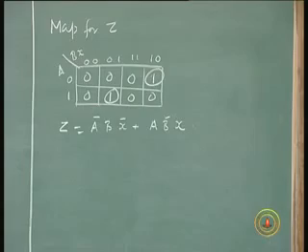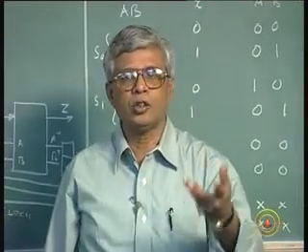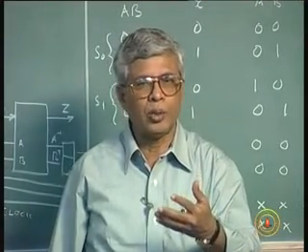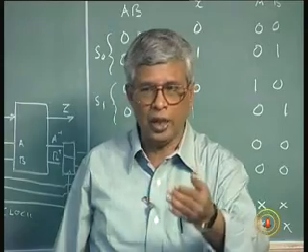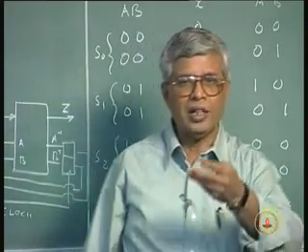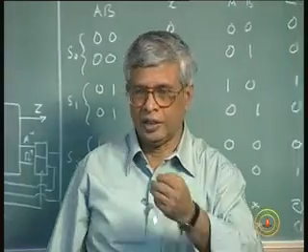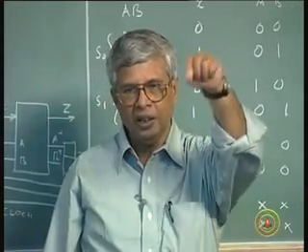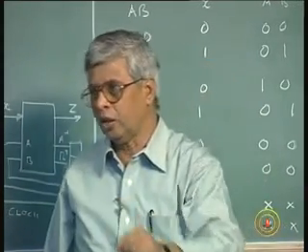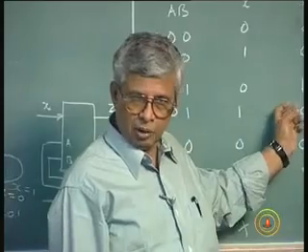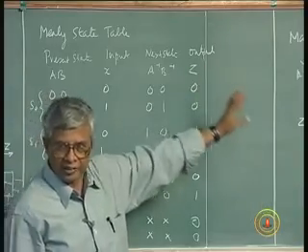When somebody gives you a system, you talk about the various states the circuit is going to be in, and the input conditions under which the circuit is going to change from state to state. You should also ask what is the output required for each of those states or each of those input conditions, and then specifically mark them in the state graph and carry it on to the state table, onto the transition table, onto the final design.